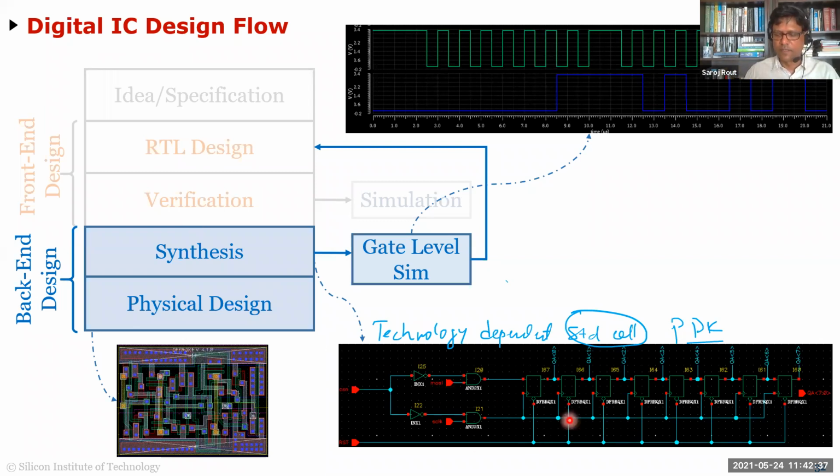Actually, this particular circuit is from their schematic. They designed it like you would do, putting in a shift register and all that. So that's a full custom design where you don't use Verilog at all. Some people, even in full custom, use Verilog and synthesize it. A lot of times, if the digital block is small enough, you just design it by hand. In the classical sense, you don't do RTL and synthesis.